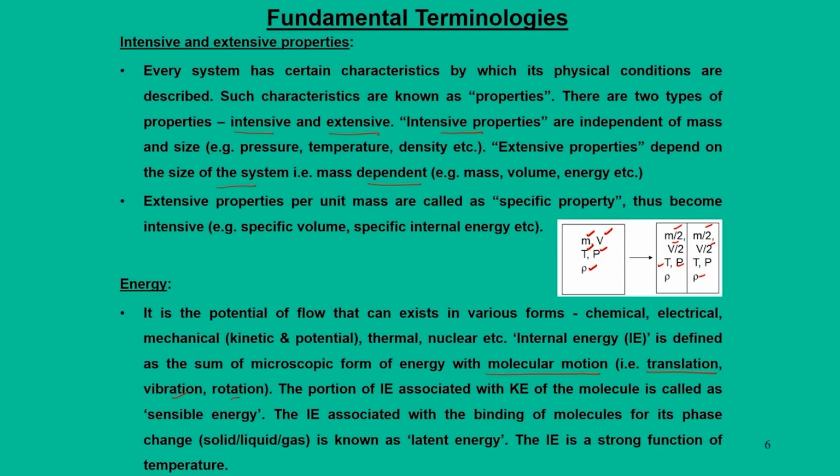When internal energy is associated with the kinetic energy of the molecules, we say it is sensible energy, and that happens due to change in temperature. When this internal energy is used for binding the molecules in their phase, and we want to go for a change of phase, then such energy we call latent energy. However, internal energy is a strong function of temperature for a pure substance, and in our entire course we will treat internal energy as a function of temperature only.